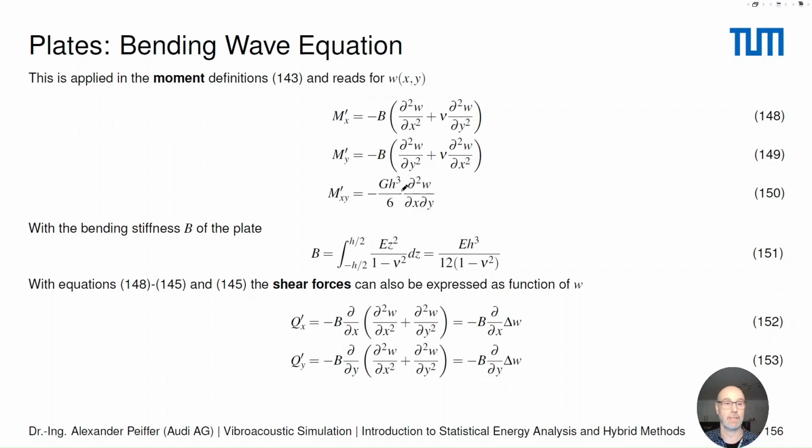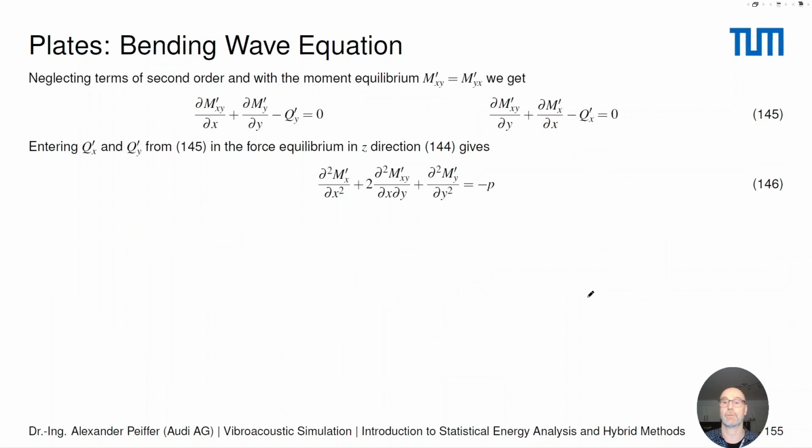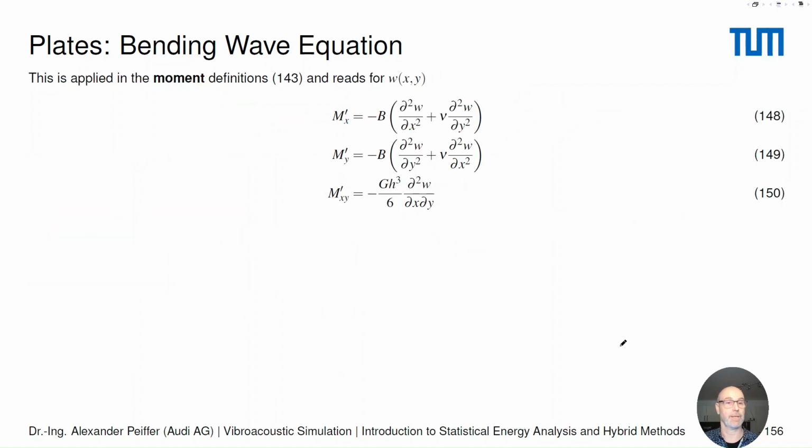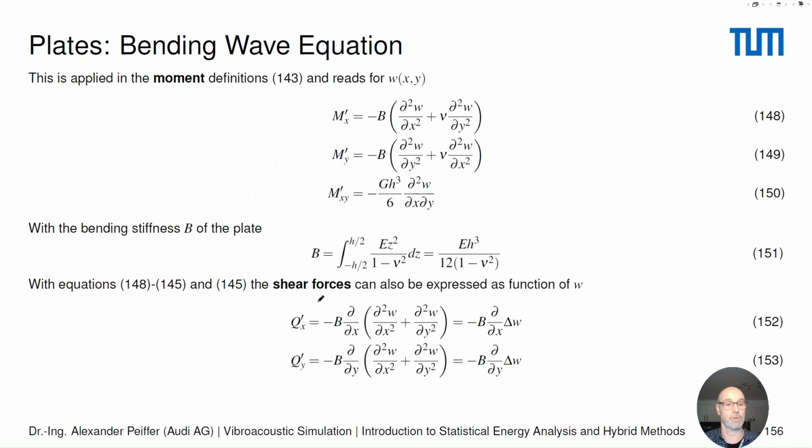With the equations here and 145, which is the relationship that relates... Just go back to show you 145, which is just the equilibrium equation. We can finally end up expressing all the shear forces also as a function of the displacement. So just to summarize this slide, that means all the expressions that we need for the description of the bending wave equation are now expressed in terms of the normal displacement. That was our goal at the end of the day.